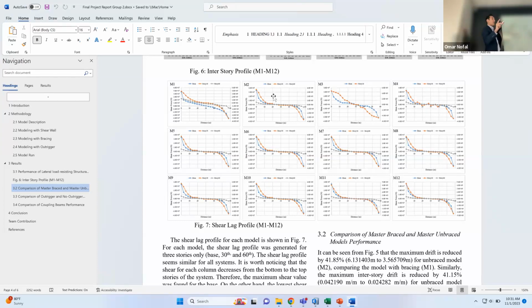You get the stress, not the tension. If you want the tension or compression, you multiply sigma by the area of the column. If you get this column, all these columns will be the same because they have the same I and the same y, so you just do it for one column. Once y is changing, you do it for all the columns on the line. Each one will have a different tension until you get to the one in the middle, which is going to be 0 because y is equal to 0.